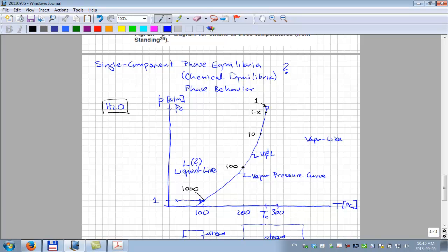And those phases, the vapor phase, the steam, is saturated. We call it a saturated phase. What is the steam saturated with? Liquid water. And we can say the liquid water is saturated. It's a saturated liquid system. But what is it saturated with? It's saturated with steam. You can't pump any more steam into that volume of liquid. So along here, we have what's called saturated vapor and liquid along that curve.